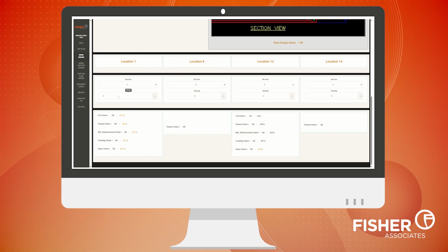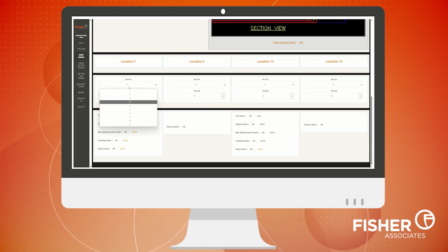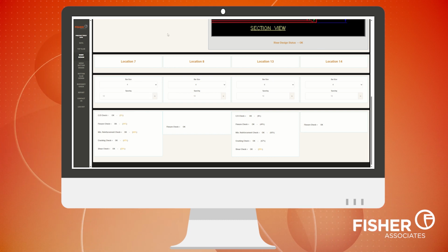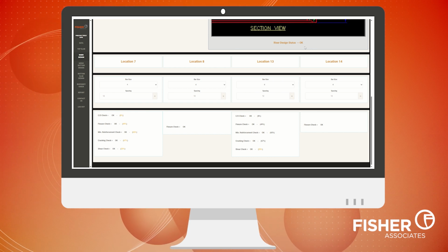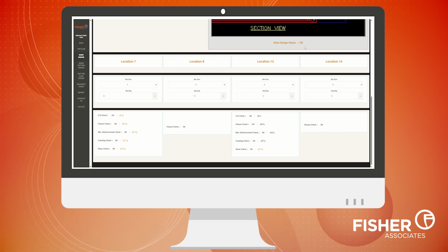At location 7, I see that the current bar size is number 5 at 8 inches spacing. To make the design a bit lighter, I'll adjust the spacing to 12 inches for this demo. This adjustment works, so I'll also test the bar size by switching to number 4. Even with the 12-inch spacing, the number 4 bars perform well, and this is a design I'm satisfied with. Just be sure to confirm that the design status is still marked as OK on the plan, so you know it's good to move forward.